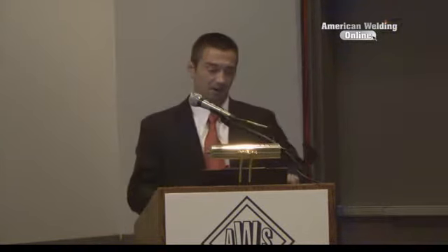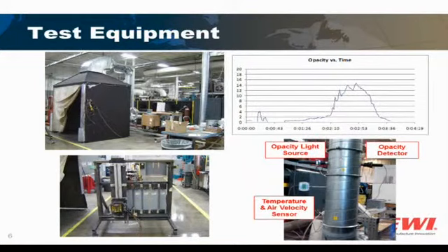And how they analyzed it is they took a baseline starting condition that maybe is above 0 most of the time. So they zeroed out the opacity graph, and then they captured 2 things. They captured average opacity, and then they captured total opacity. Total opacity is a percent opacity-second. So they basically added it up for all opacity values over every quarter of a second.